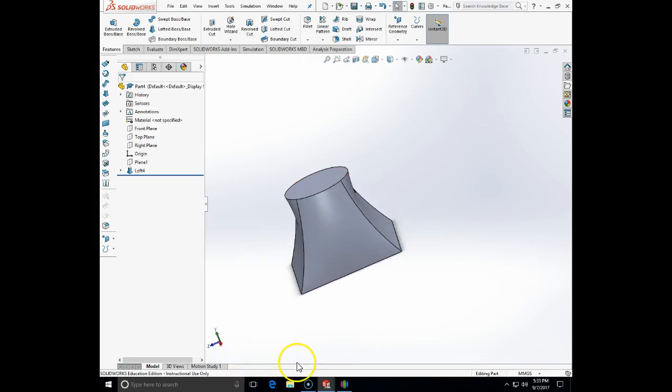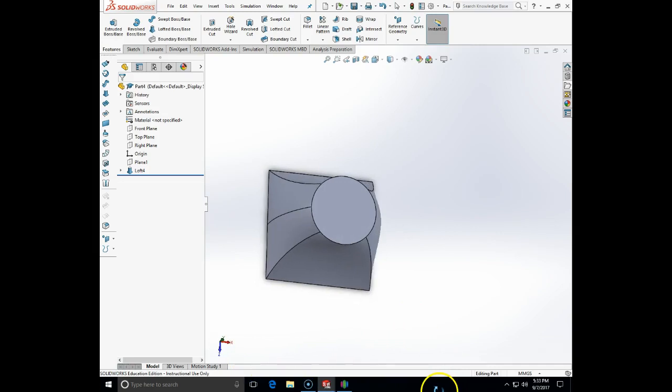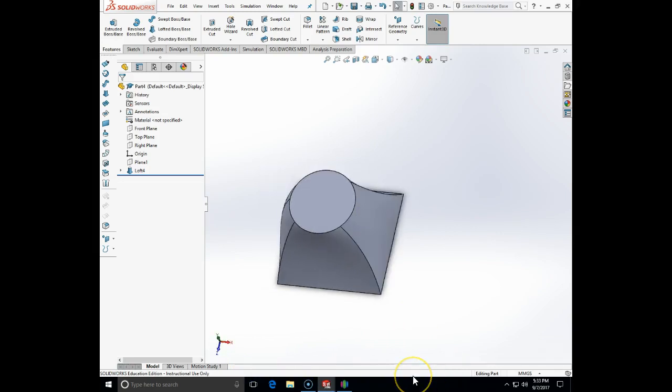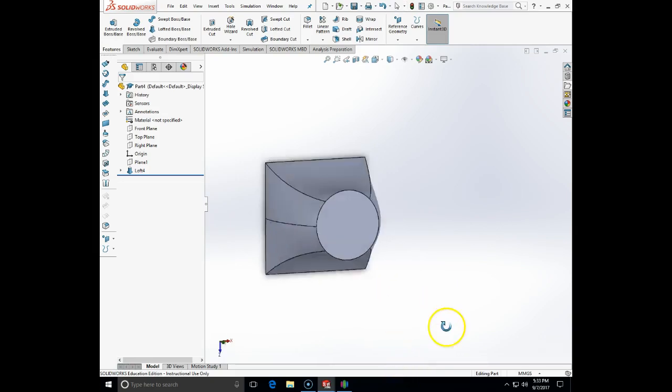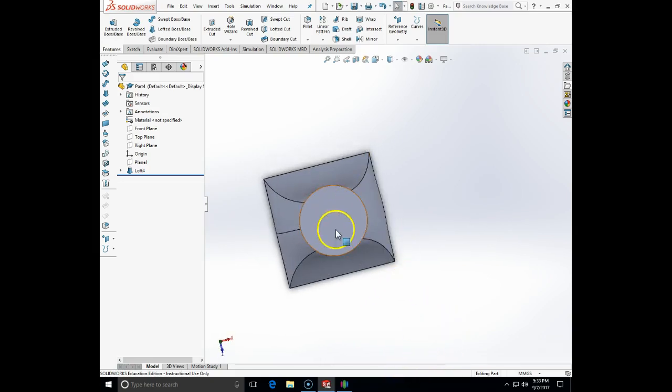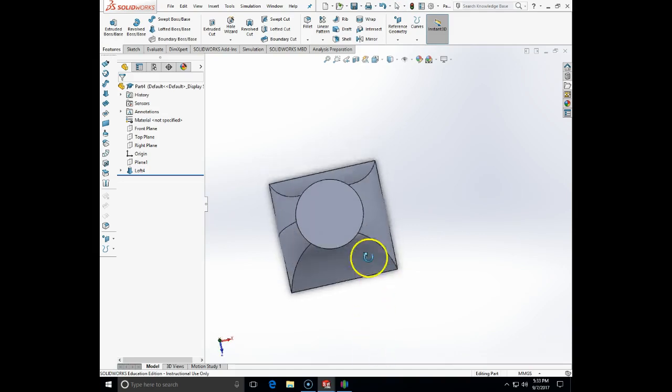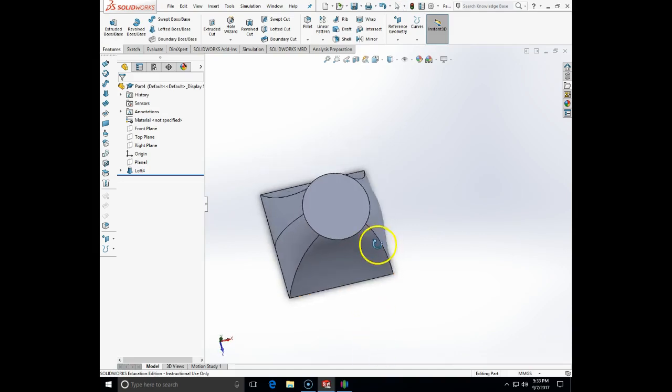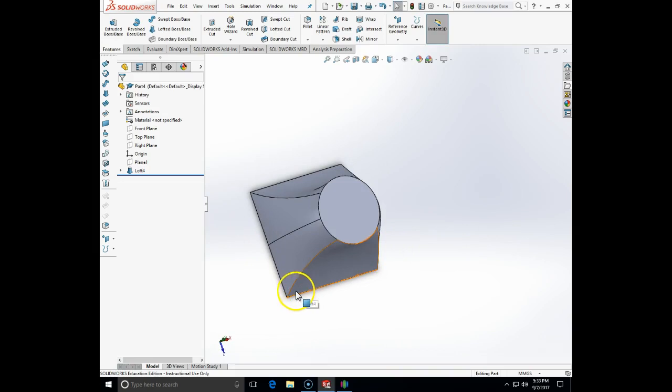So I was able to create this fairly complex geometry just from a circle and a square in reality, by using a guide curve to define how the change of one cross section progresses to another cross section. Okay, now it's your assignment just to complete the first elementary loft.